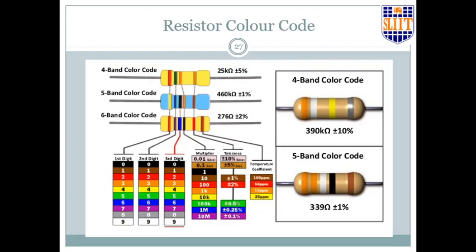When you go up to 11,000 feet, the temperature goes to several tens of degrees below zero. So if you work with room temperature, 24, 26, 30 degrees, there will be trouble and the estimation will be wrong. So you need to know the accuracy based on the temperature as well.